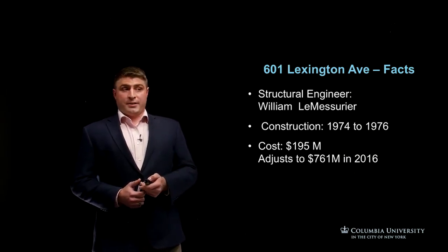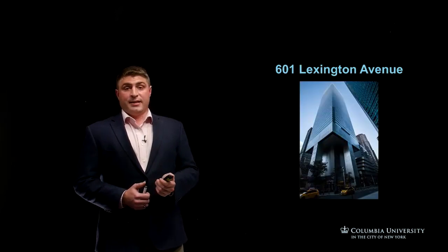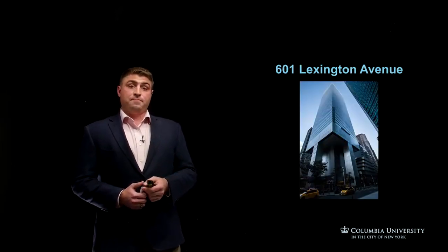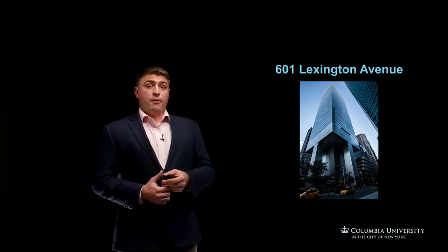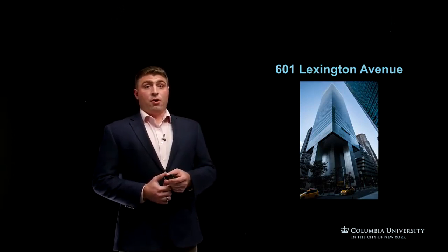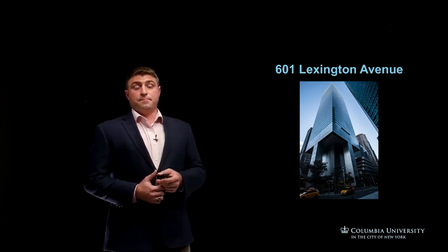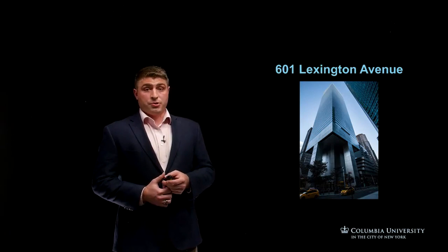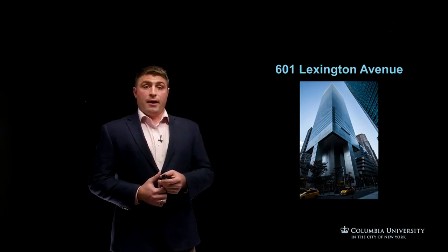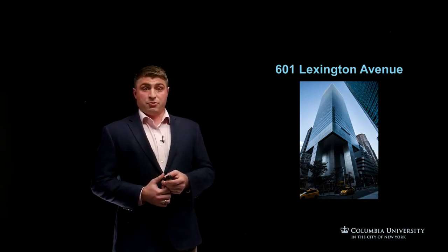The most interesting fact about this building is that it contained a major design flaw. Diane Hartley, an undergraduate student at the time, was preparing her thesis on the building and called the structural engineer to explain her analysis yielded the following conclusion. Perpendicular winds were accounted for and did not present a threat. However, quartering winds, or those that hit the building at its corners, were not accounted for and pose a very serious threat to the structure.